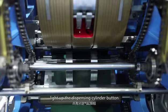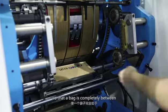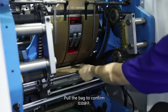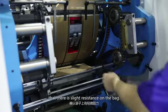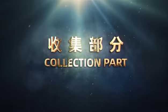Click the dispensing cylinder on the touch screen to light up the dispensing cylinder button. Rotate the machine so that the bag is completely between the delivery wheel and the drum. Pull the bag to confirm that there is slight resistance on the bag. Bag collection part.